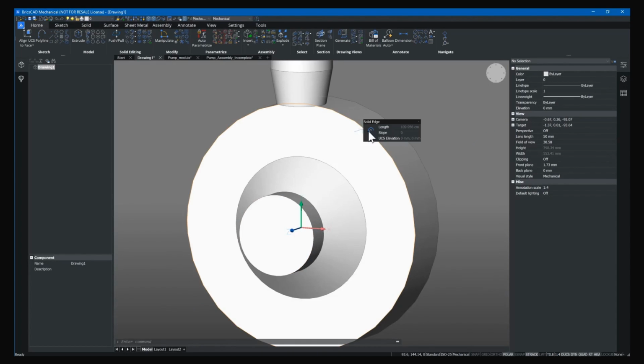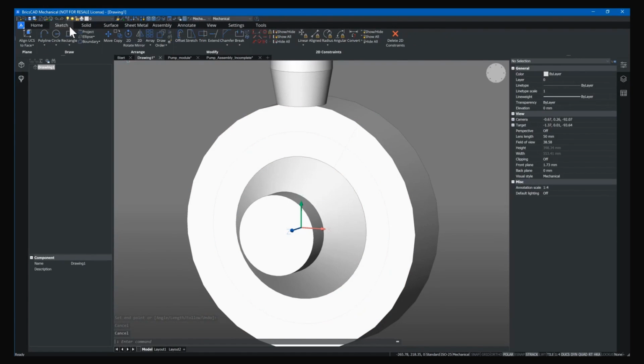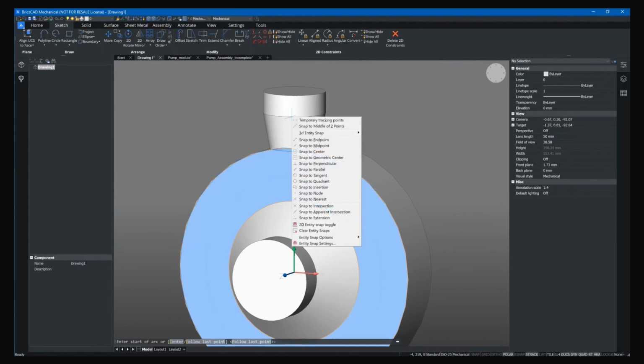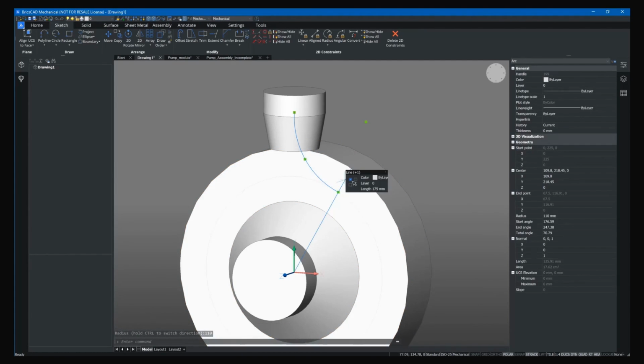And now the next step will be to connect the top part with a seamless, smooth transition to the main part of the solid. So I will offset the outer edge of it inwards, and I will create this line to create an intersection point. If I select these two lines, you will see that. I can then create an arc from the top part, which I want the transition to move from, and then snap the end of the arc to this intersection. Define a radius for it. It might be difficult to see, so I can select them for you to see better.